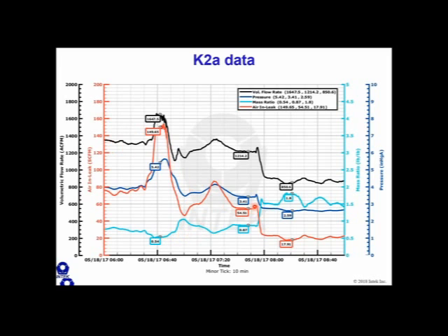And so we went along here. We did find the air in-leakage at this point. You can see it's kind of widely varying. I'll show you why that is, but there's an issue there. But anyway, right here is where we shut off the air in-leakage. The air in-leakage came down, the water to air mass ratio went up, and the back pressure came down here.